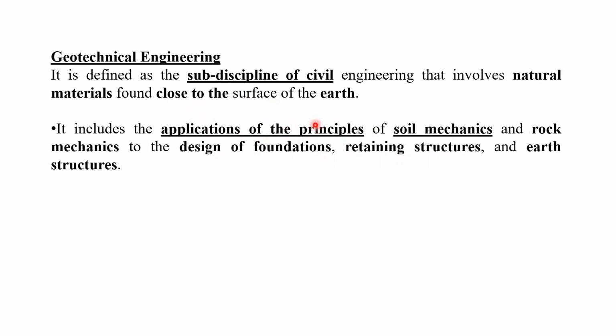So those 2 points come under the application of principle of soil mechanics. So those two parameters, physical properties, as well as what type of forces is going to work on the structure, whether it is a vertical force or a horizontal force, we have to cover all those points in the design of foundation or the retaining structure or the earth structure.